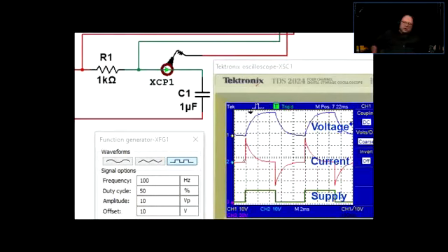Remember, when the capacitor is not charged, the electrons are going to rush through the conductors connected to the capacitor to charge it up until it fills to its capacitance limit, and then it's going to stop flowing. So at the beginning, it is going to act like a short circuit. That's why I put a little current limiting resistor, just so the current doesn't flow as fast, because if that happens, you can have problems. Right? So the purpose of this resistor is just to slow down the current, and it's called a current limiting resistor.